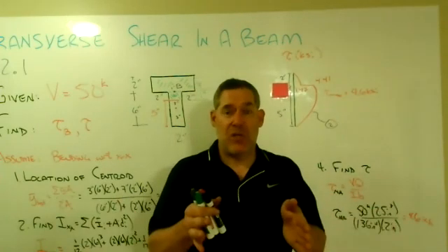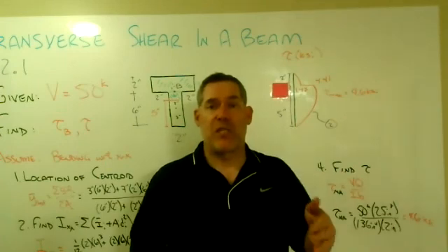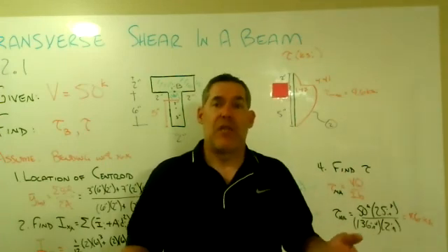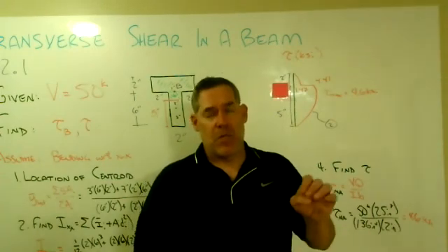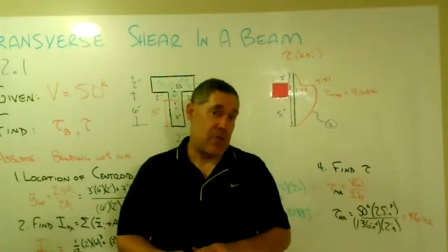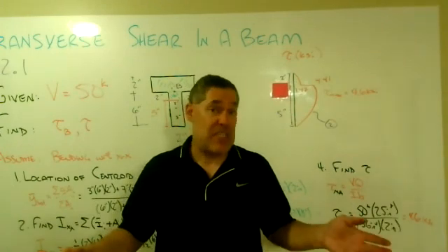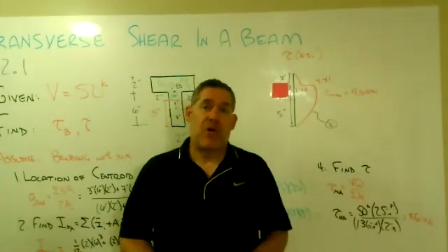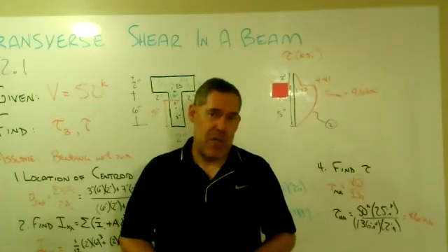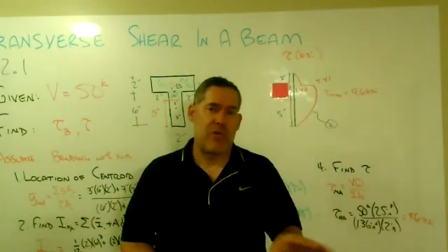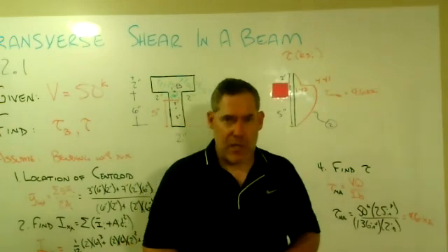But essentially, the shorter the beam or the closer a point load is to the end of a beam where a support might be located, then that's where you tend to have other things that may control the design of the beam. And one thing we haven't talked about at all is the stiffness of the beam, which in certain cases will be more important than the strength of the beam. Right? A lot of different things can go wrong in our members, and we'll explore some of those as we go along in other lessons.